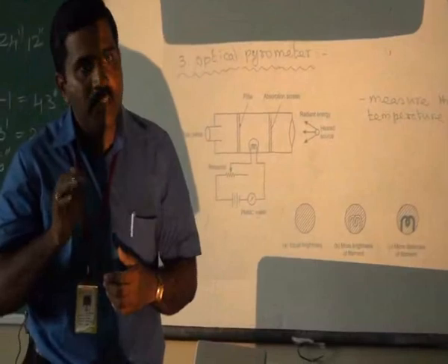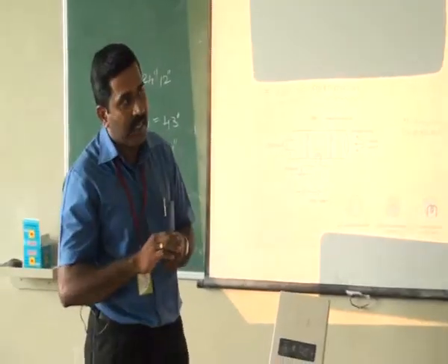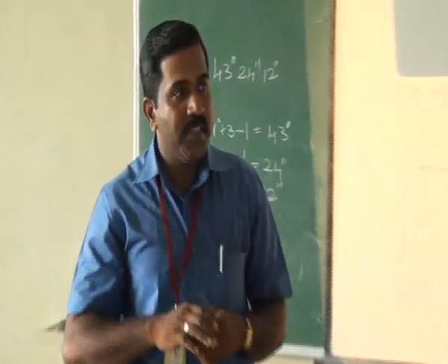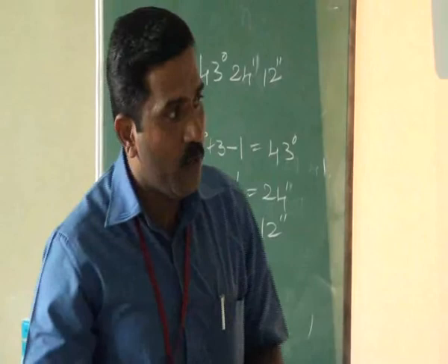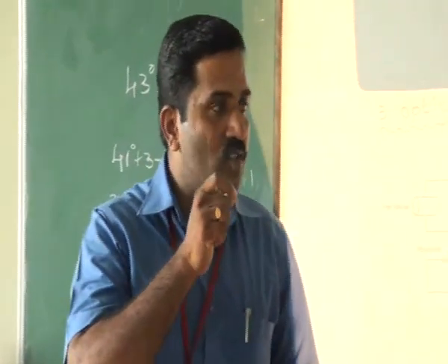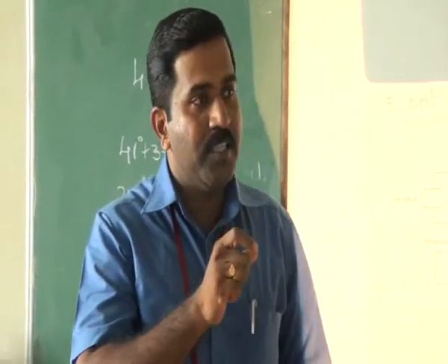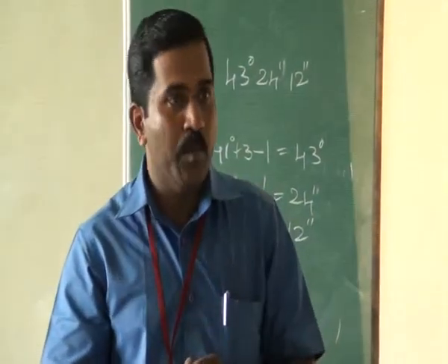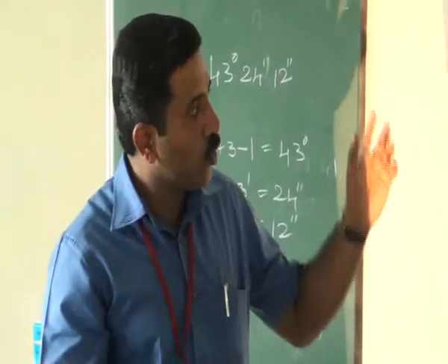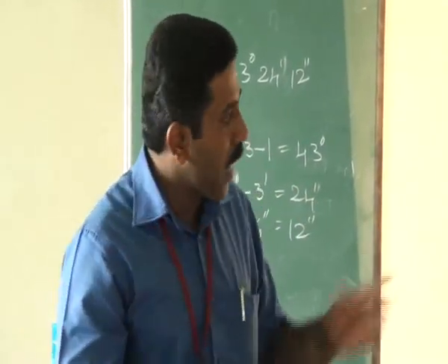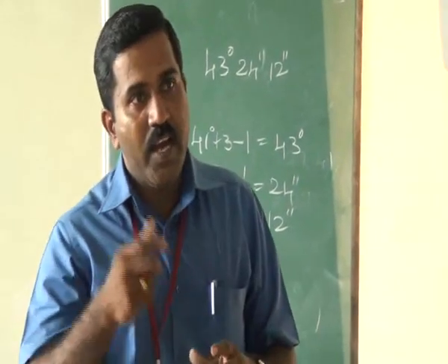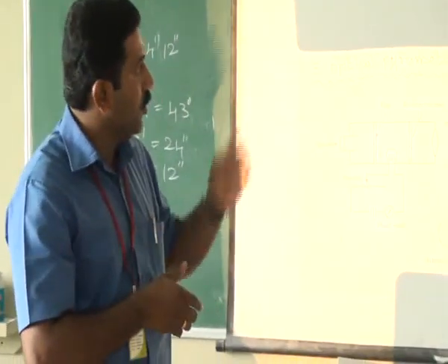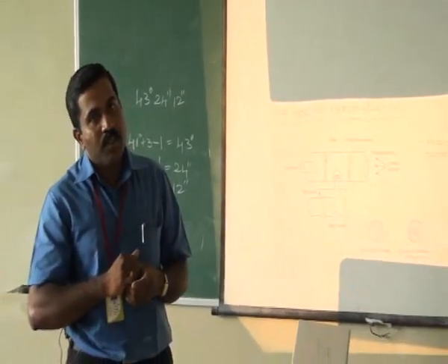Normally thermometers measure lower temperatures, but a pyrometer is used to measure higher temperatures. Higher temperature levels we measure by using pyrometers. Directly we cannot touch the component in higher temperature measurement instruments. We only observe the radiation from the temperature sources by using various methods. The thermocouple and the absorption screen are used to observe the radiation. Then we measure the component. So this is the temperature measuring instrument.